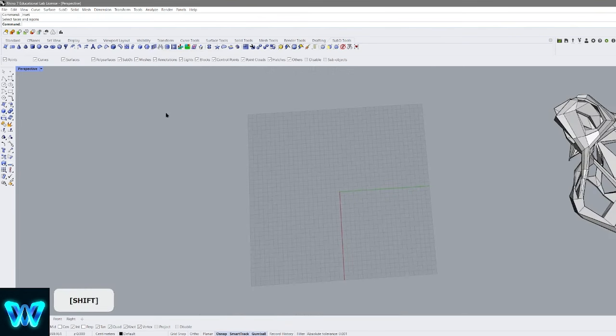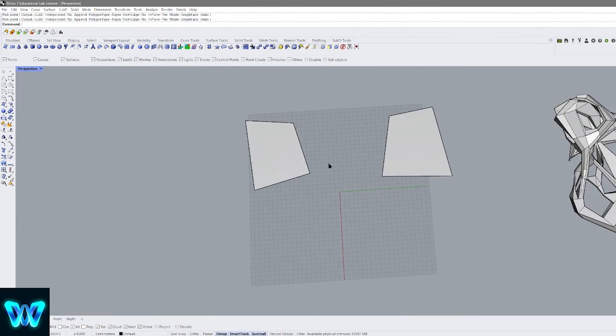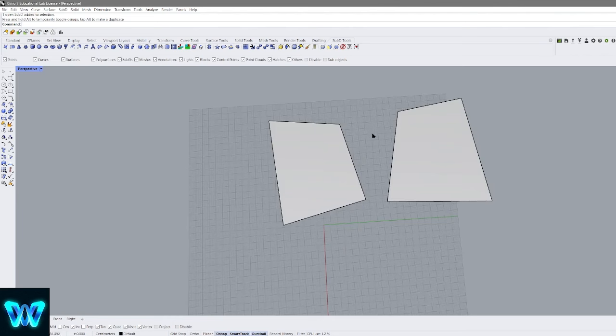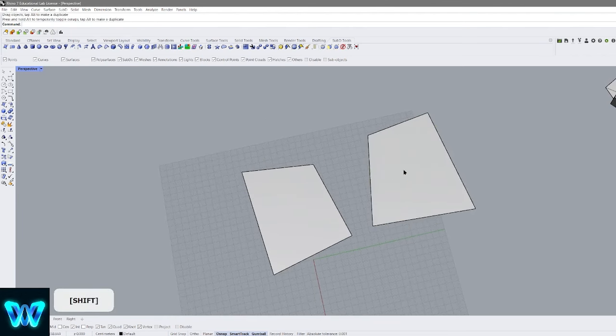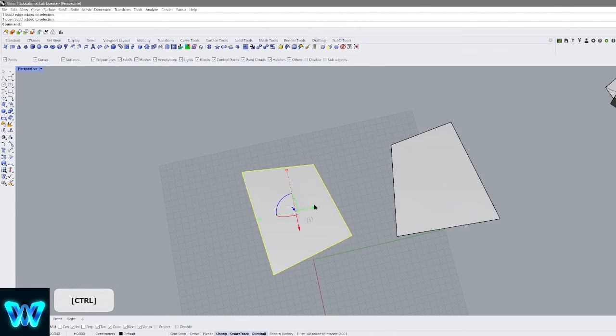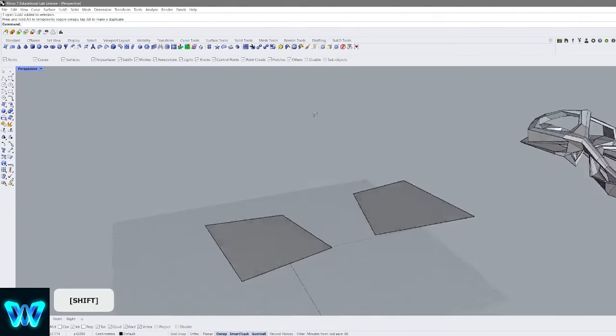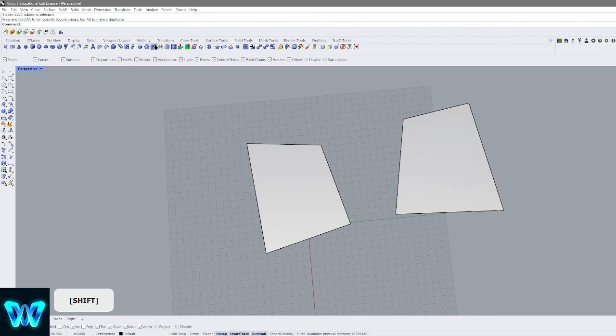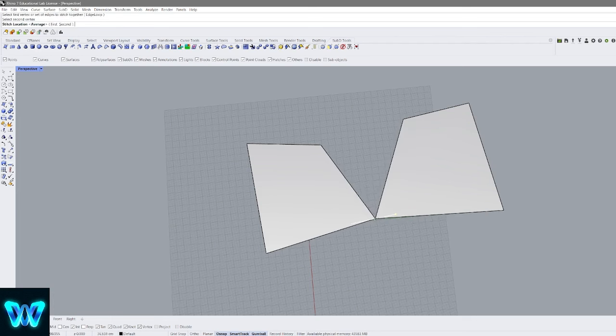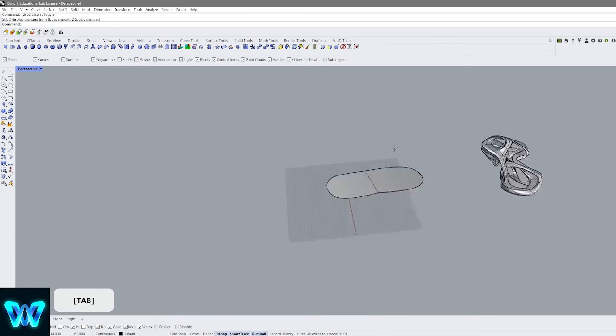Stitching is also really important because, for example, if I have 2 SubDs and I want to join them, there's many ways to do this too. So if you have 2 SubDs you want to join, you can always loft them. Well, not lofting them, because that won't join them. But one thing you can do is stitch. So you can stitch an edge together. Actually, you can stitch a set of edges, but the way I do it is I just stitch vertex. You see that I just stitch a vertex with another vertex, and now I have a combined face.